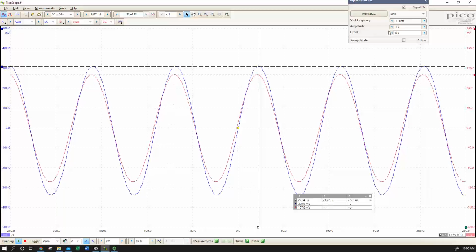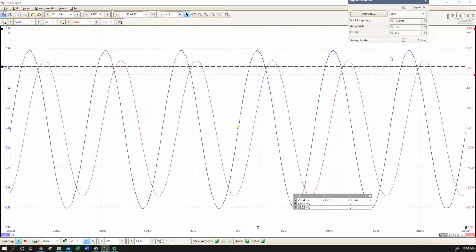Okay, let's go ahead to a higher frequency. So as we go to higher frequencies, the reactance of our capacitor is going to drop, and the reactance of our inductor is going to go up, and we should see our signal B start to shift over to the right. The peak will go to the right, and so we'll go to a different lagging leading relationship. So let's go to something that's clearly on the other side.